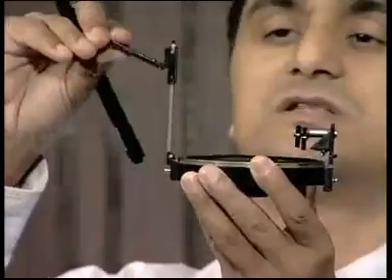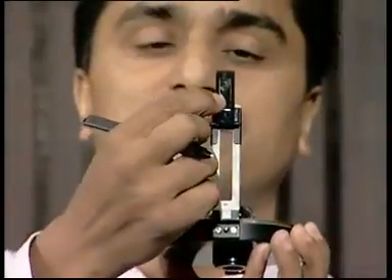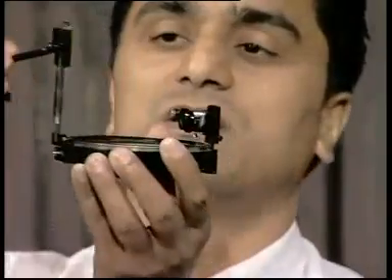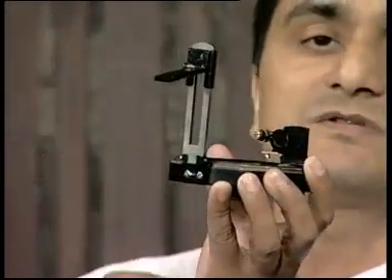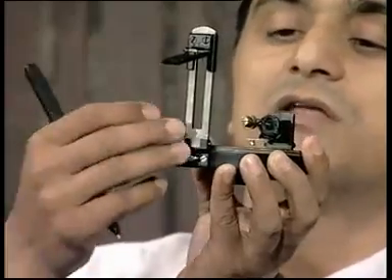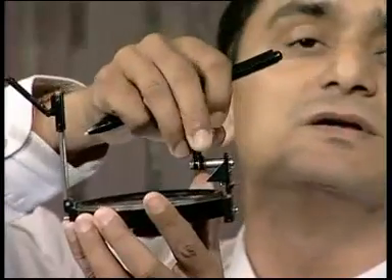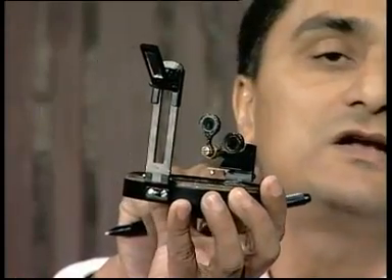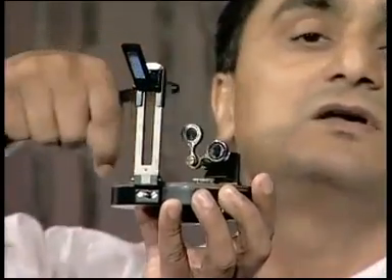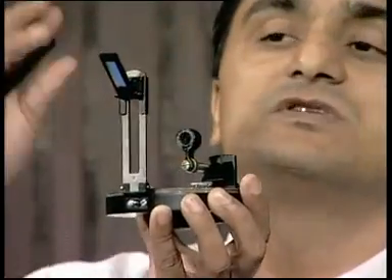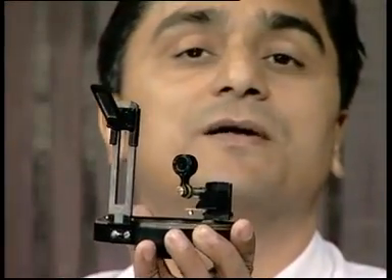Okay. Well, over here you will see there is a mirror also. This is a mirror fitted here. We can tilt this mirror, and the use of the mirror is if the line of sights are inclined. For example, the ranging rod is not horizontally in front of me, rather down there. So I can see the ranging rod in the reflection through the mirror. So this is why we use the mirror. Also we have got some color glasses here. Because we are looking through the slit, we need to see the readings here. So color glasses help us to reduce the intensity of light sometimes when it is required.